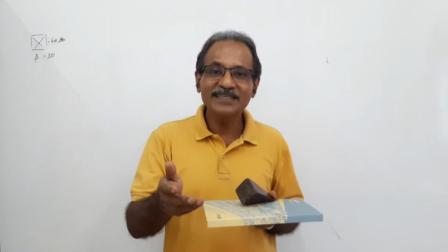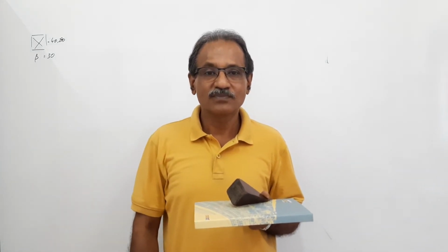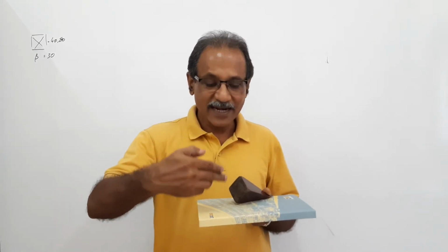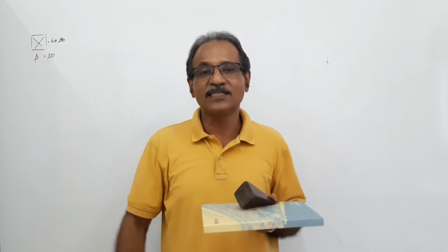That question is same as your question: the square pyramid is lying on HP on a slant edge with the plane containing the axis and slant edge perpendicular to HP and making 30 degrees to VP. It's the same thing. In your question, beta of axis is given, but that is nothing but phi of the slant edge. So the question can be framed in two different manners. That is for your information.